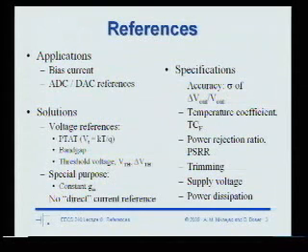So if you need a current, you generate a precise voltage, then you drop it across a resistor, and you get a current. Well, you don't have precise resistors, right? So if you need that current to be very accurate, you're forced to use an off-chip resistor. Note that the current is proportional to the absolute value of the resistance.